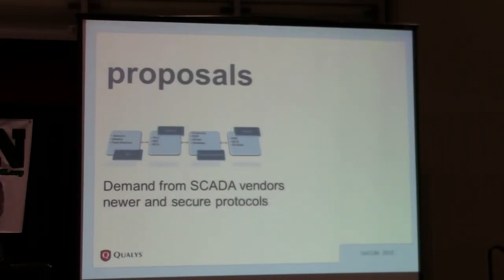Demand newer protocols from your SCADA vendors, because older protocols, as we saw, were not really meant for security, and if you are using those, you are just wide open. So demand newer protocols, and also when you get newer protocols, make sure that you are using them. In more than one instance, we have seen a check mark saying we have secured DNP3, we have secured this, we have secured that. But when you do an assessment, still the old protocols are being used. So, okay, you bought the new software, but it was never really configured to make use of these new security features. So make sure that's done.